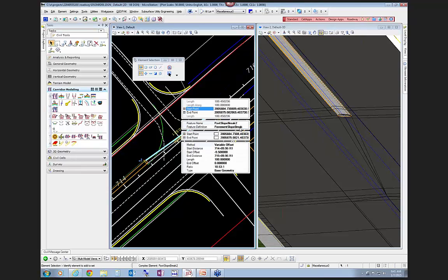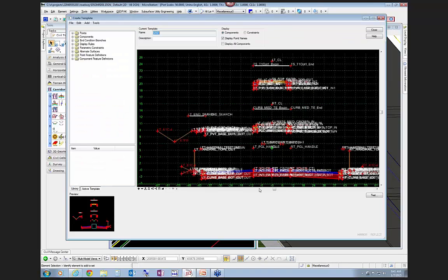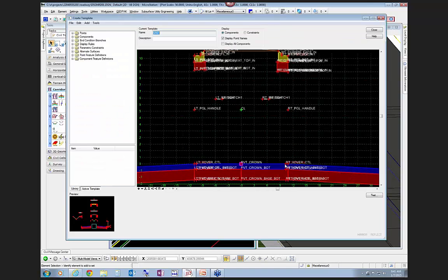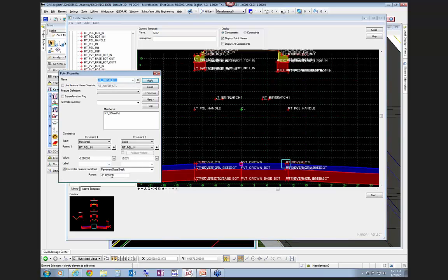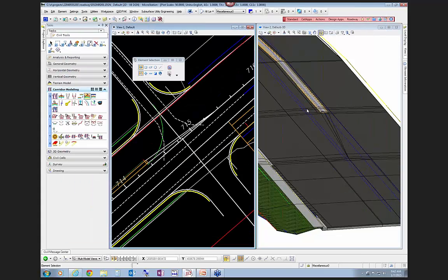And that corresponds with the point on the template that's looking for, again, this point right here is looking for a pavement slope break, and it's set to look across the median for that. And then that will control the crossover in that situation where you have to go from one traffic separator to a normal crown. Now, if you had a traffic separator on the other side, opposite this intersection, what you would do is, instead of having these lines go to the crown, you would basically have them go to the other two sides of that. Okay.